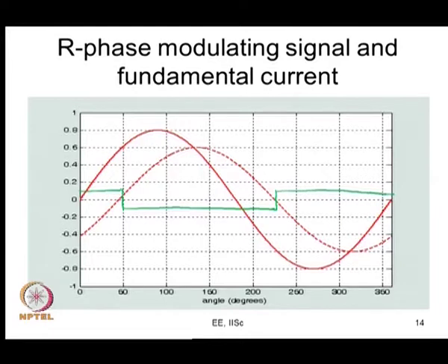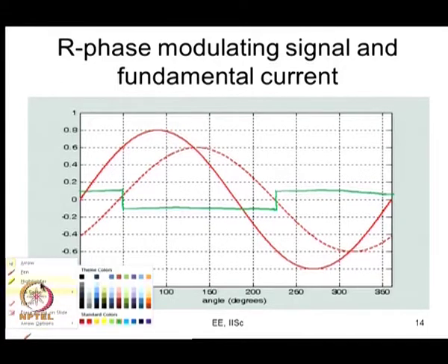So, what is this error? There is an error between the instantaneous actual pole voltage and the instantaneous ideal pole voltage. So, we have considered that error between the actual pole voltage and the ideal pole voltage. After that, we have averaged it over every carrier cycle. So, how much will that value be equal to?